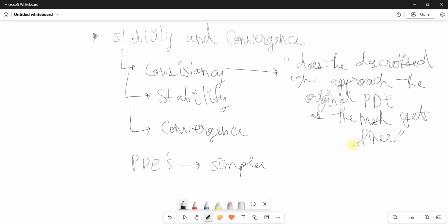So what we check in consistency is whether both these give almost the same value, and as your mesh gets finer, you have to be more accurate. Now if your mesh is coarse, it is bound to have some inaccuracies, right? So what we check is that as your mesh gets finer, do these two values come around the same line? If they do, then it is consistent, and if not, it's inconsistent, right?